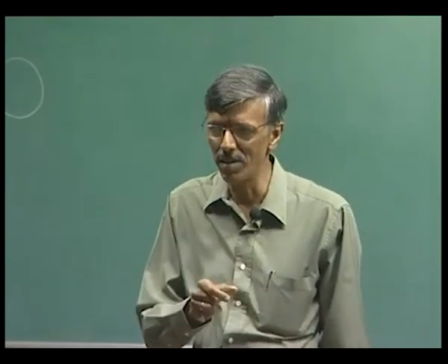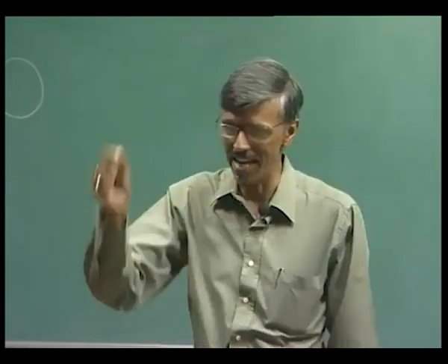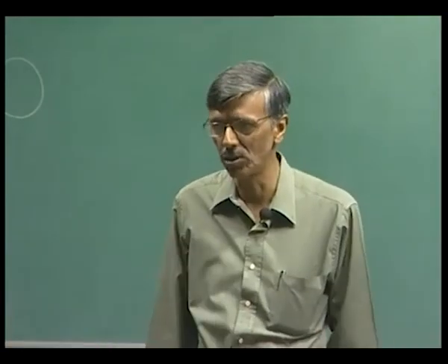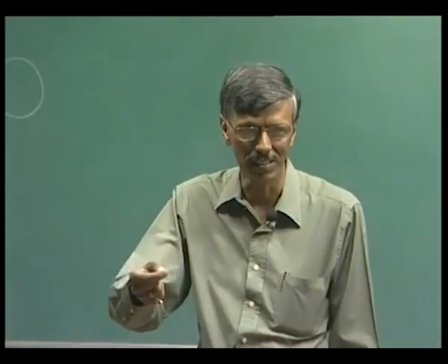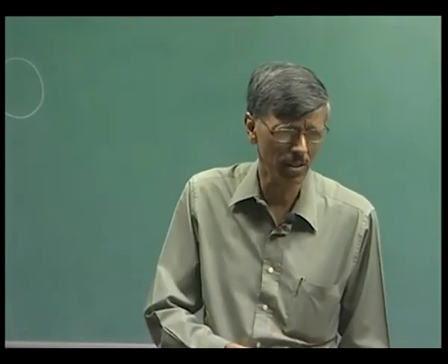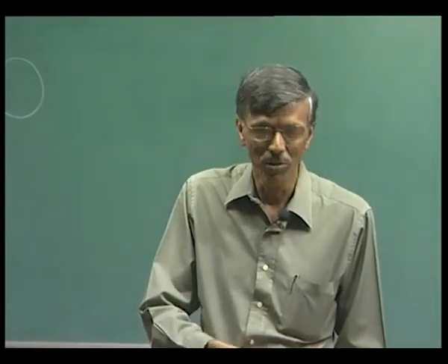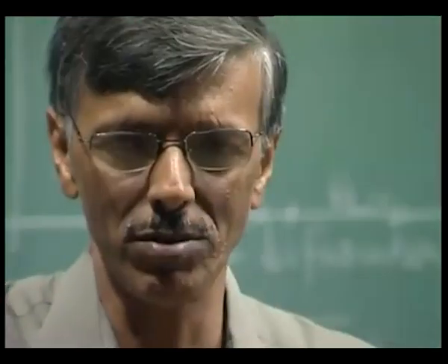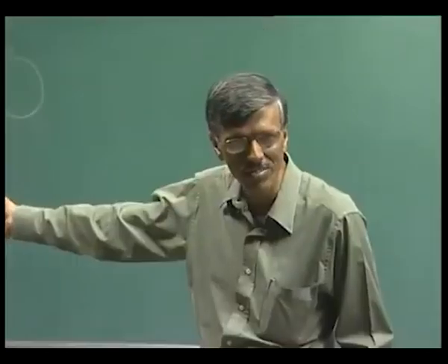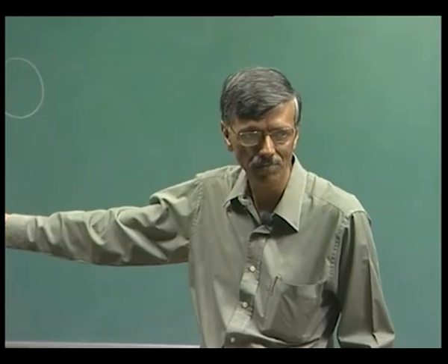So, if I have a temporal instability, well, it is there at a fixed location. From there, the disturbances are going to grow in time if I keep measuring it. But then, do we see such a thing at all? We see eventually some disturbance growth and then that is thrown out. That is exactly what we are seeing in the bluff body wake, right.